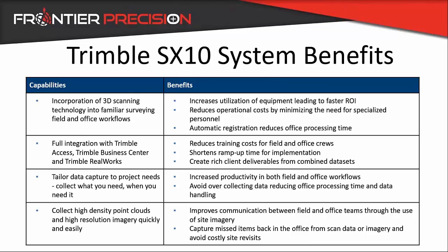Some of the benefits of an instrument like this are the incorporation of 3D scanning technology into a familiar workflow. That's a huge benefit and something that a lot of people have been asking for. It actually is a prohibitor of a lot of organizations not using scanning because they can't use it in a traditional workflow setting. For instance, you have to set up targets and register the scans, and that takes a lot of time, and it creates some inefficiencies, and it's new to a lot of people. It isn't a standard survey workflow.